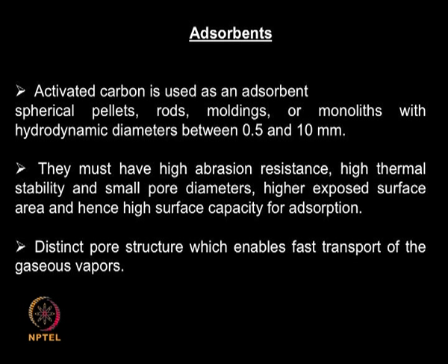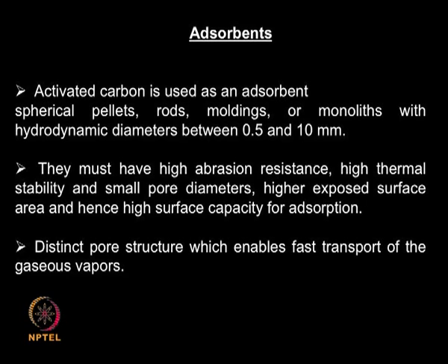When you are buying or designing an adsorbent material, you have to keep these points in mind. All the adsorbent materials have good pore structures, some of them have very uniform diameter pores, and there is a lot of research done in designing these pores of uniform diameter. You do not want a very large distribution of diameters, from very small to very large pores. If you have very small diameter pores, sometimes the gases might not enter, so those pores become useless. So, maintaining the diameter to a very uniform value is a very important challenge when designing adsorbents, and designing uniform diameter pores is very important if you want to have a manufacturing product.